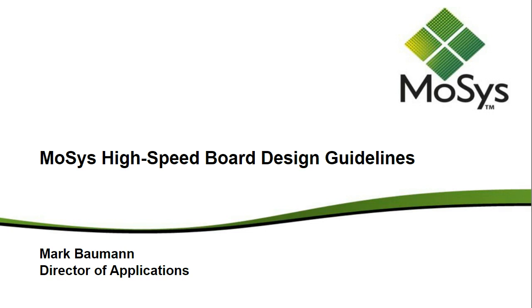And we introduced a family of products called Stellar IP. We have a lot of cosmic names like Blazar and Quasar. So the IP is a packet classification family, including LPM routing IP and exact match IP and high complexity ACL IP. So it's often used to replace TCAMs. Instead of using external TCAM, you can embed this IP in your FPGA and leverage your on-chip memory or external DDR or HBM. And so we're now in two product families.